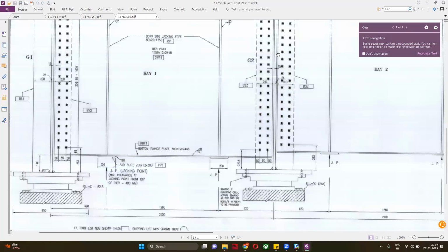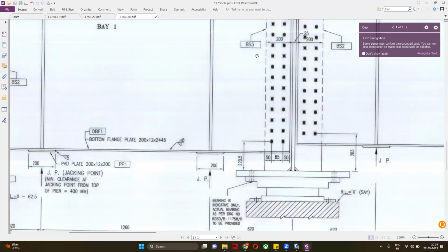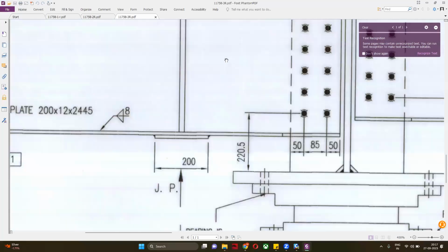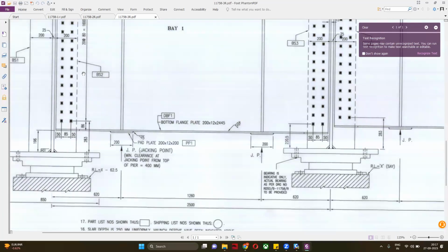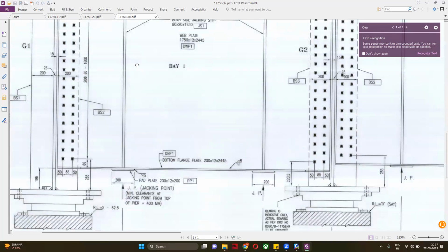So we assume that you can create the modeling at the center, because in the end it doesn't matter if you are modeling the shear connection a little bit eccentric. Only shear will be provided. No bending is there, so it does not cause any moment due to the eccentricity. If I model at the center or a little bit eccentric in steel, it doesn't matter. But it should be a little bit according to the drawing.